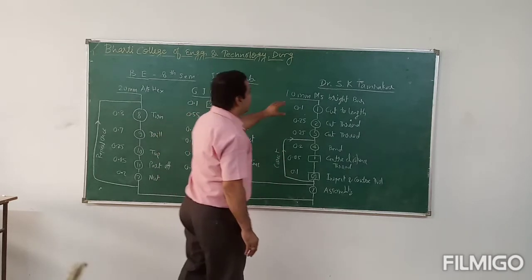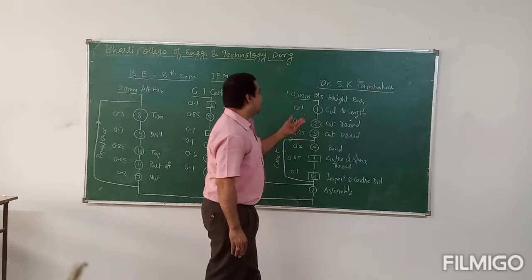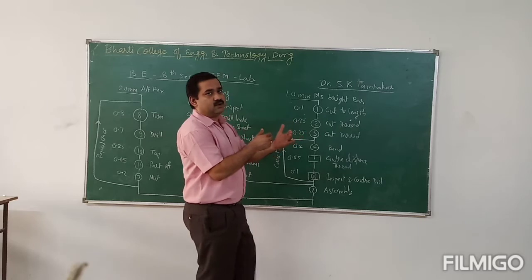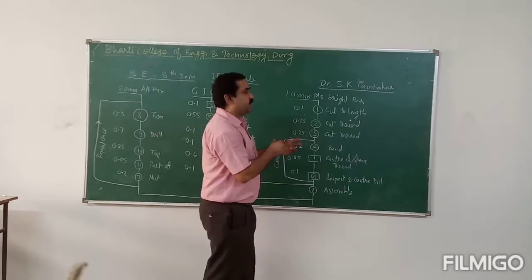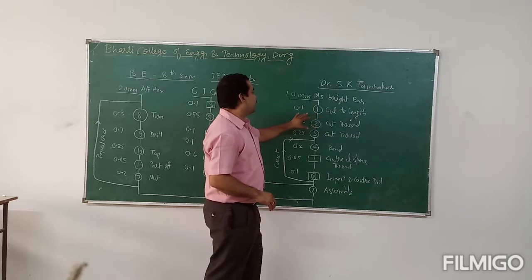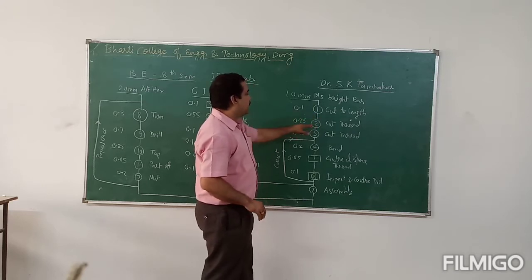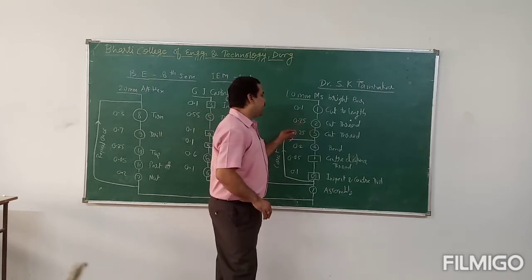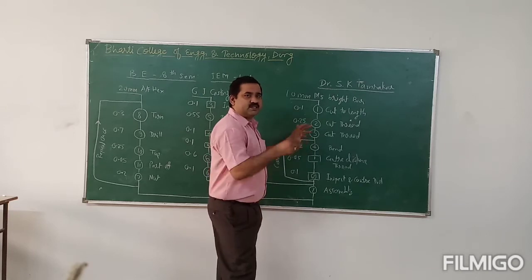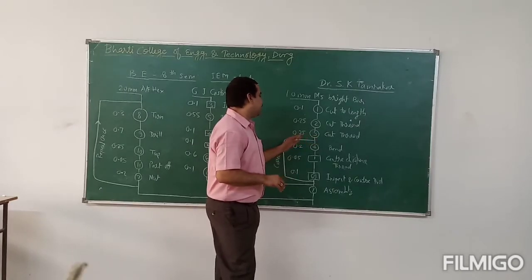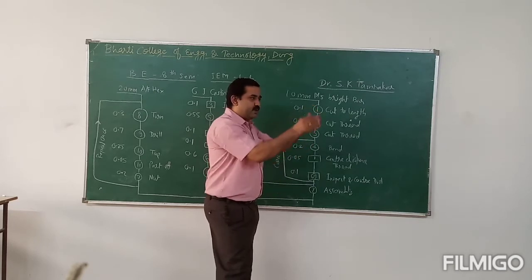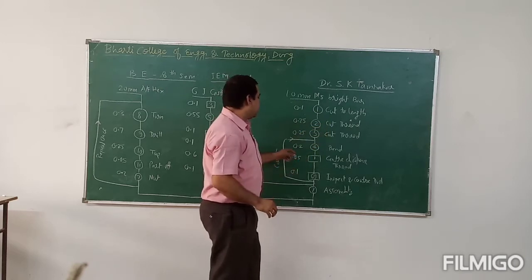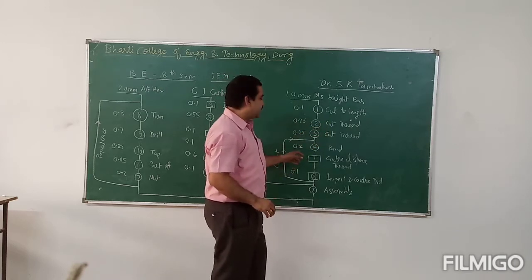The 10 mm bright bar is taken and first cut to the exact length we need to clamp the pipe. Cut up to that length, that takes 0.1 seconds. Then cutting thread, that is the second operation, 0.25. Again some thread is also cut on the second part, so this also takes 0.25. Then bending, the bright bar is bent. For that, the process takes 0.2 seconds.